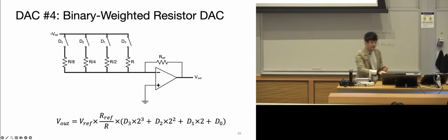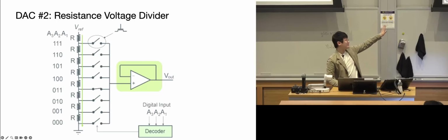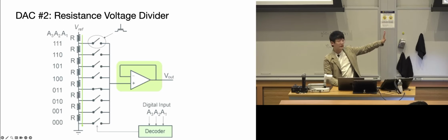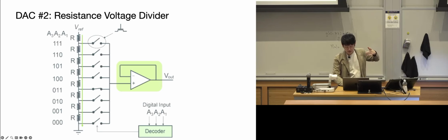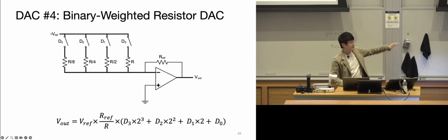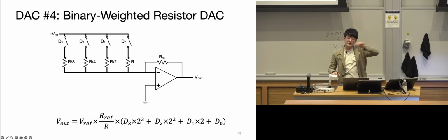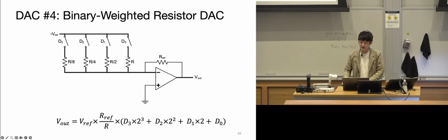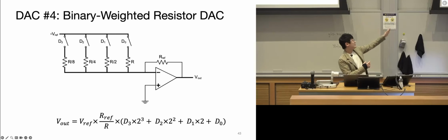Like if we go with the most OG design of the DAC, you can still have a very precise version of this, although each R might not be exactly the value you wanted. However, for the more complicated ones, for example these ones, chances are they will be fabricated in different batches. So any of the little variances can add up in these types of configurations. But again, this reduces the number of resistors you need by a margin. So, trade-offs.